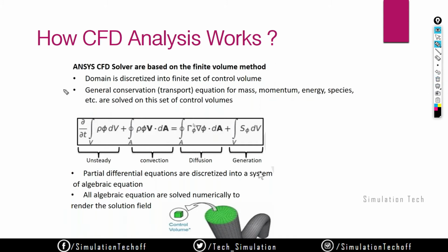Okay. Basically in CFD analysis, we have so many terms like walls, domains. The domain is nothing but the region of analysis. For example, if you have a fluid, we call it a domain. That fluid domain is discretized into a finite set of control volumes. The discretization is nothing but meshing, and you are all familiar with this term, what is meshing. We sometimes call it discretization. We break an infinite stage into a finite stage through meshing.